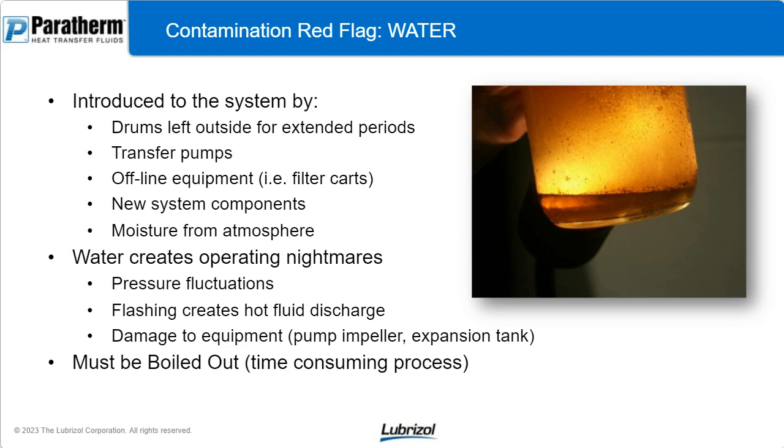Another big red flag: water. Water gets into a system, it's going to cause big problems. If you're operating above the boiling point of water, which most of these systems are, you're going to have water flashing off. You're going to have water steaming off.